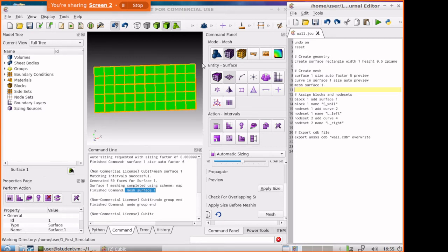So now that we have our mesh, we need to define the boundaries and also the volume. So we want to assign names to the volume or the surface and the boundary in order to be able to refer to these surfaces and curves in OpenCFS. So let's say this line here, I want this line to have the name L left, and I want to assign in OpenCFS, so that's what I'm defining in the XML file.